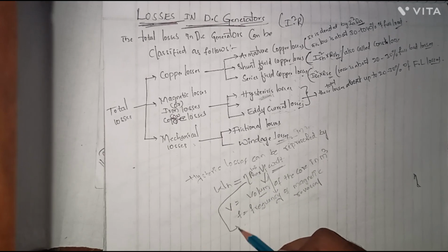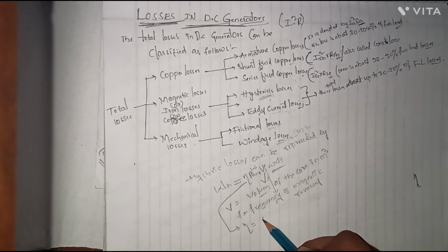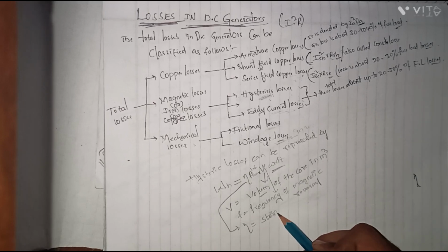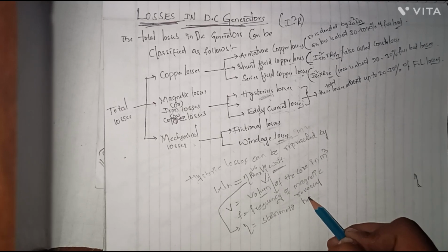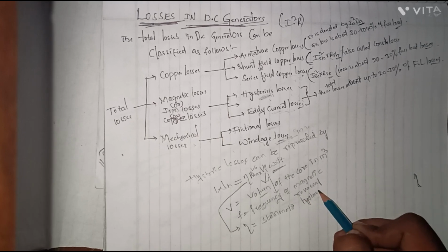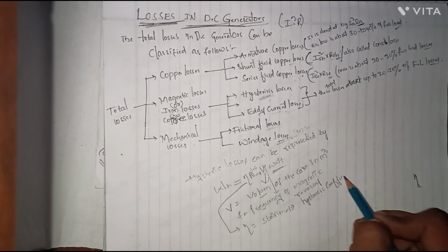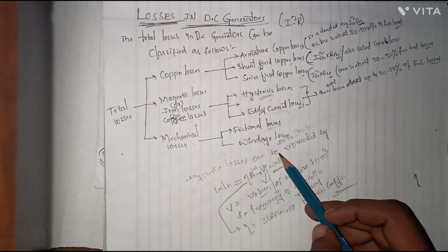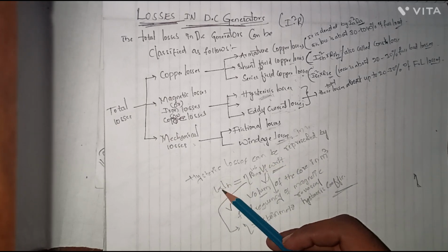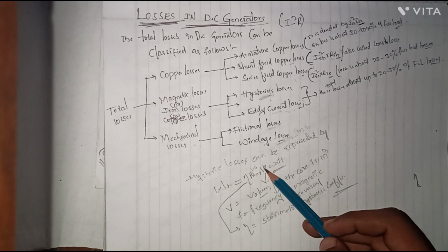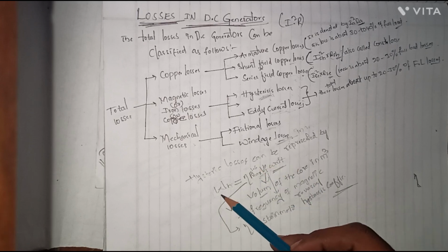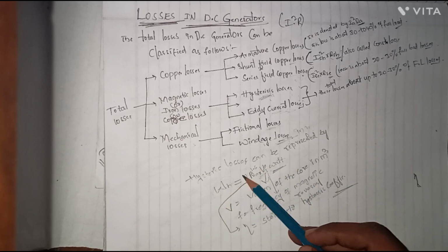Efficiency అనుకుంటాం మనం, బట్ ఇక్కడ వచ్చేసి eta is the Steinmetz hysteresis coefficient. Okay, see here, hysteresis losses represented with WH equals eta, maximum flux density power 1.6, volume, frequency. Okay, ఇక్కడ వచ్చేసి this loss depends on volume and grade of iron, maximum value of flux density.